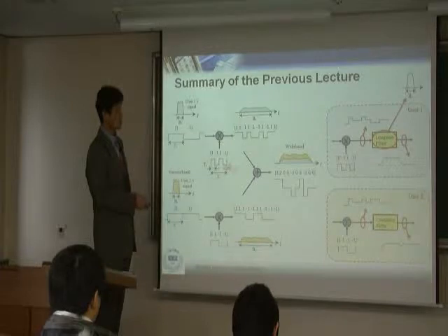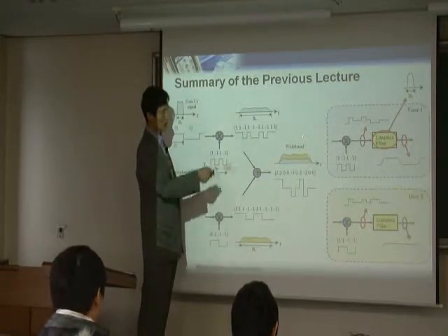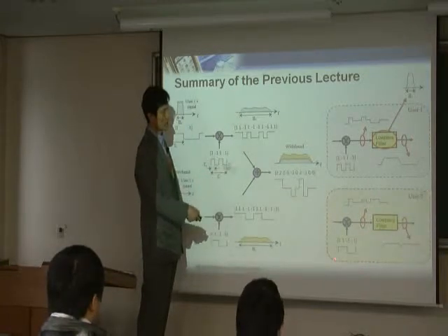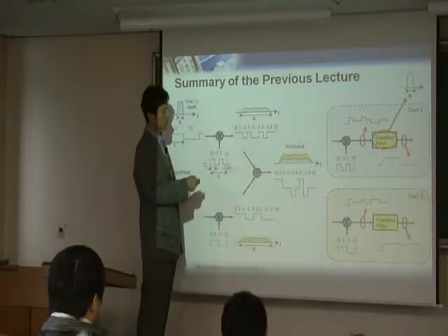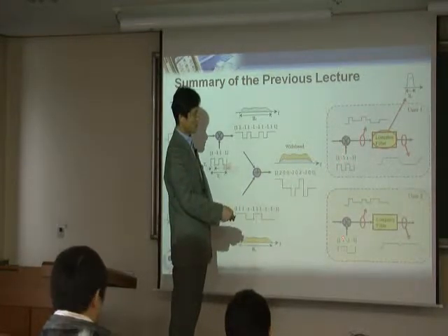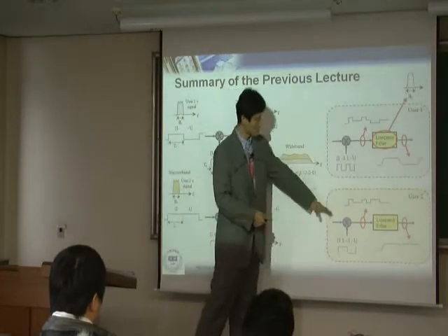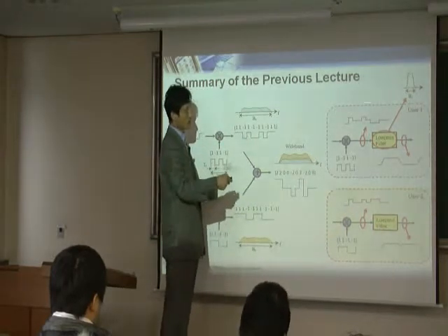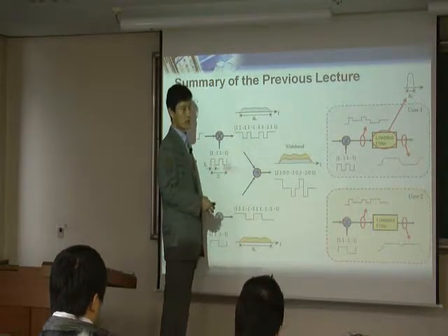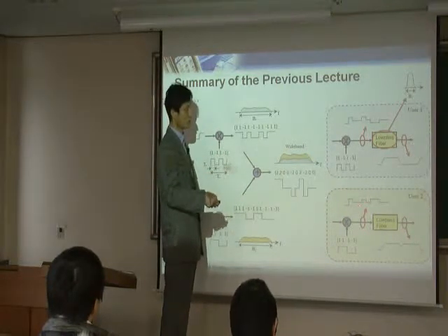When you transmit this, and user 1 also transmits, these two are combined over the channel, and this is what is received by the base station. This whole thing is done in the base station. The base station receives this signal, which is a mix of these two, and then multiplies by user 1's code and user 2's code independently. This is the received signal, and it goes both ways. Each of those is called a channel card. In the base station, you have multiple channel cards, and each channel card typically does these things.